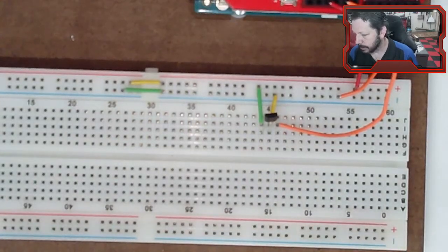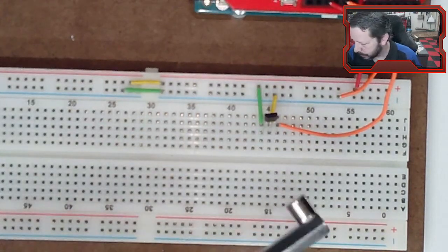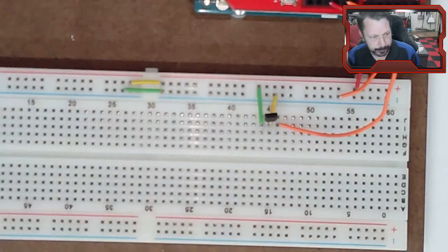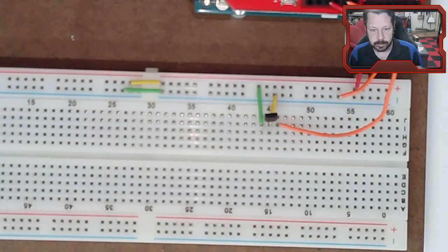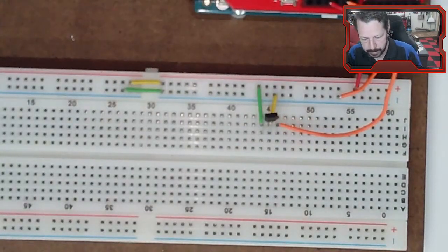Some Hall effect sensors are just kind of digital, and they'll detect the presence of a magnetic field, whether or not it's large or small. It doesn't really care. It's just, is it there or not? This one can actually give us a little bit of information about the strength of it. So let's get some Arduino, since we're running off the Arduino here. Actually, let's look at the data sheet for it first.